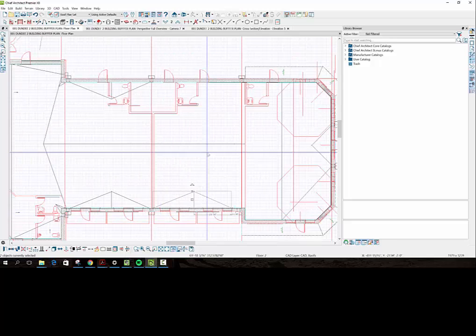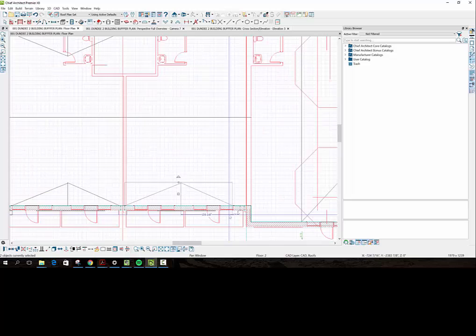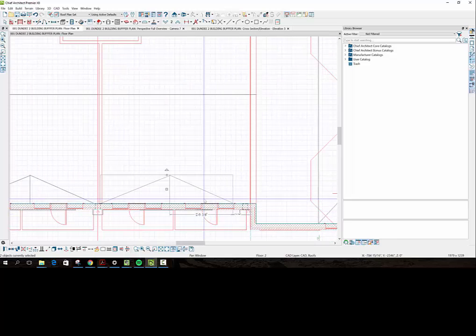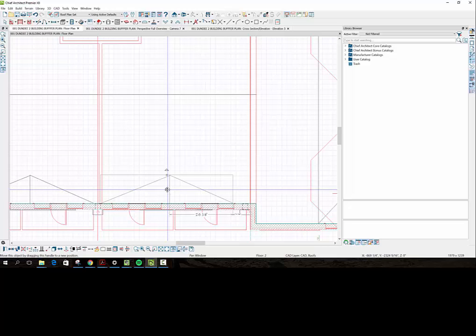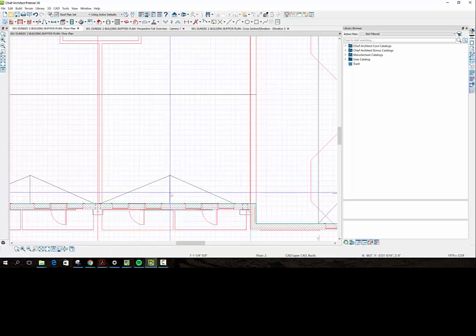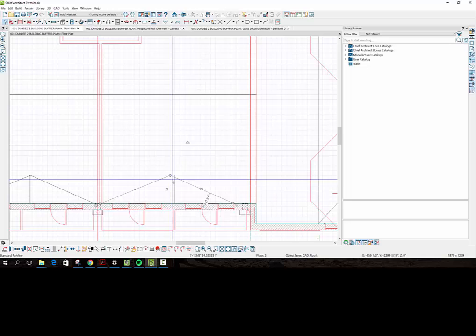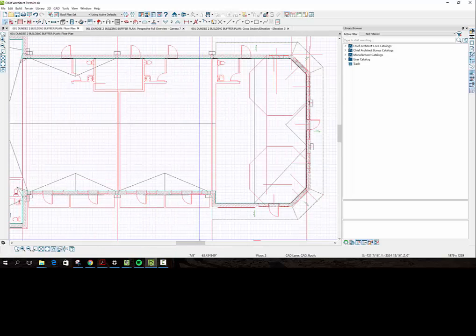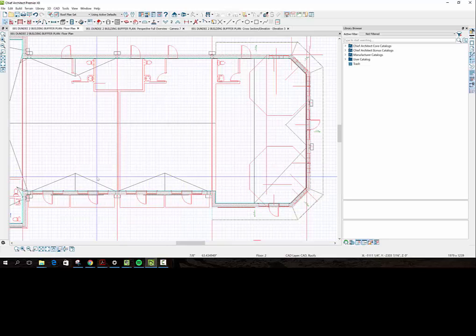All right. Oh, because these are just different stuff here. What we'll do then is slide this cricket down to the halfway point. I'll figure this out with the carpenter, how to make these crickets. This little plywood, I think this is going to be our insulated panel. We'll slide down, and the crickets will be built on top of the insulated panel in the field.